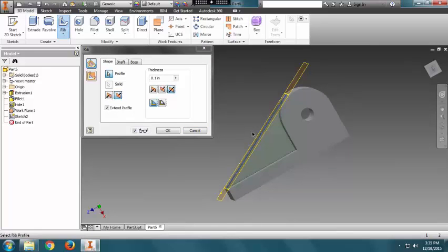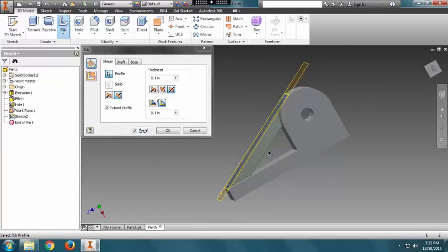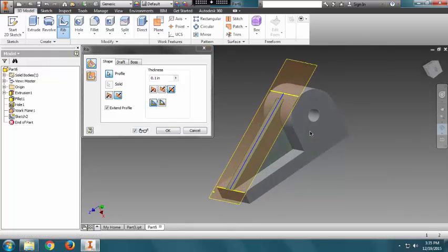Click on the line. And there are two kinds of ribs. One is a solid rib. I have a solid rib here which fills in the whole surface, and there is the other rib which is like a hollow rib which connects only the edges. So that edge is this one. You see there's no solid here. So we want this to be a solid rib. So this is a solid rib, and the thickness, so make sure you rotate the component a little.